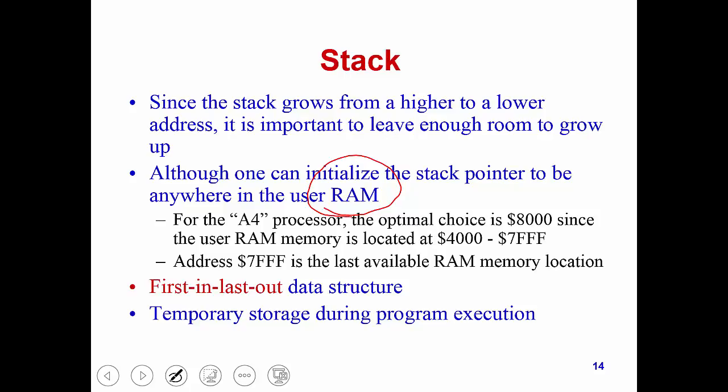Of course, you cannot initialize memory which is ROM or EEPROM, read-only memory which contains the machine code of instructions. You cannot do that. You can only specify the part of memory in RAM as a stack, because if it's ROM which contains the machine code for instructions, then you are never allowed to change it.